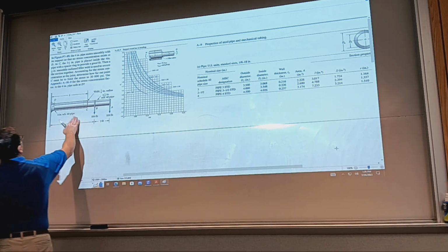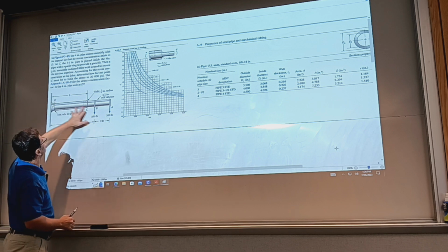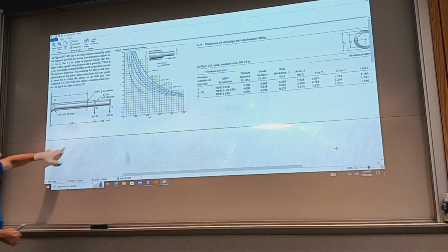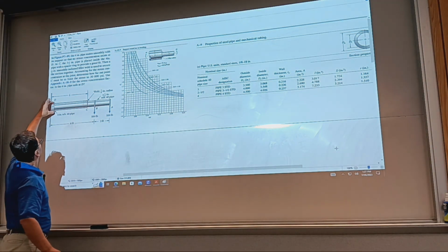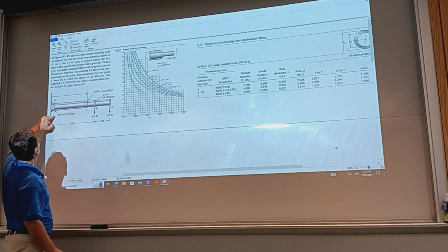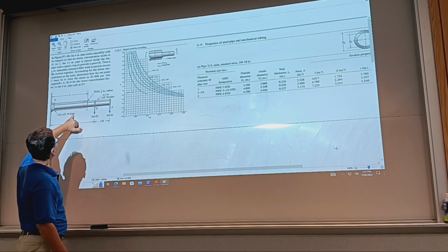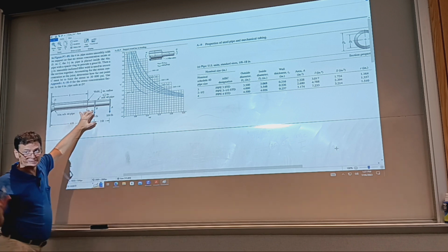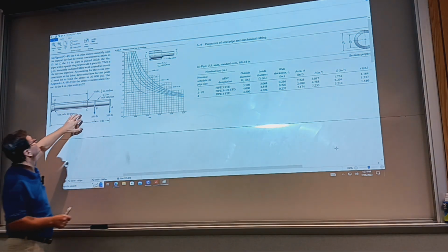So this is a cantilever with a generous fillet radius. This is where the concern about stress is. And you have unknown lengths. We need to find this out. 4-inch inside diameter pipe, Schedule 40 pipe. For pipes, the inside diameter is the main concern because they are meant to transfer fluid.